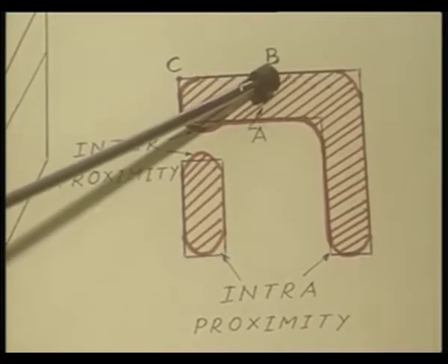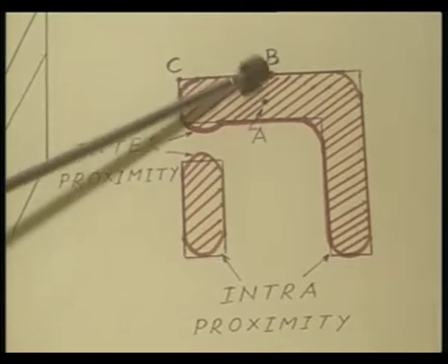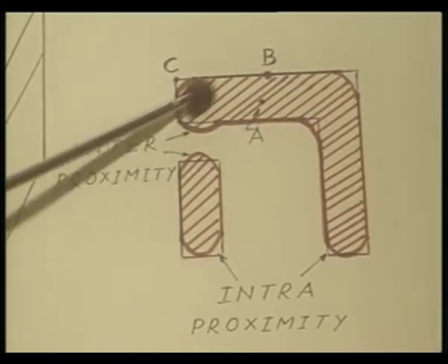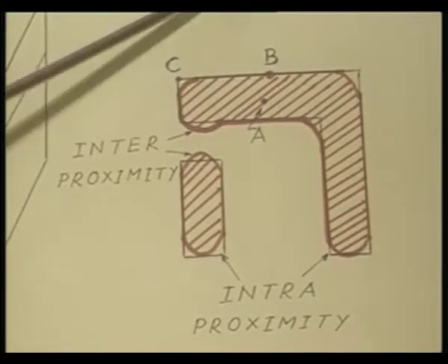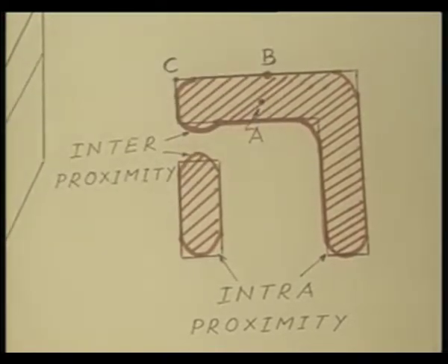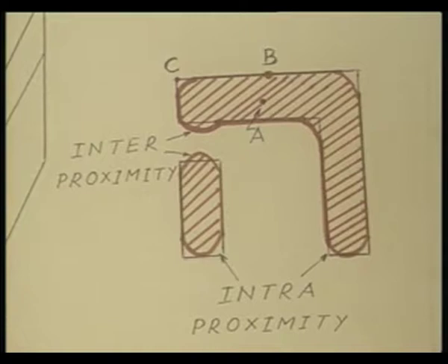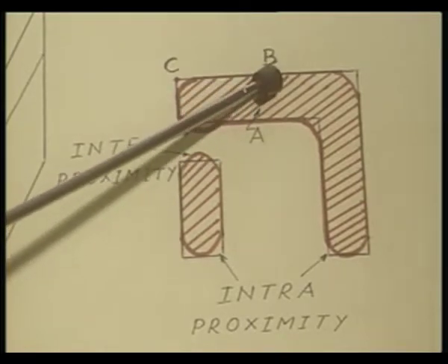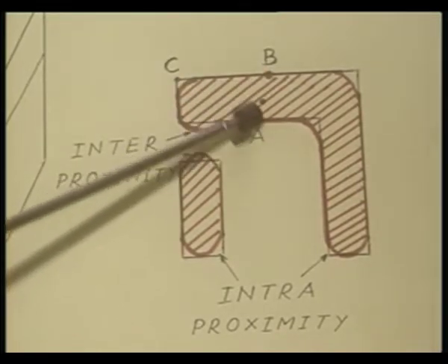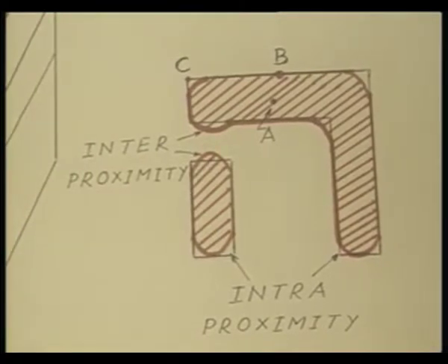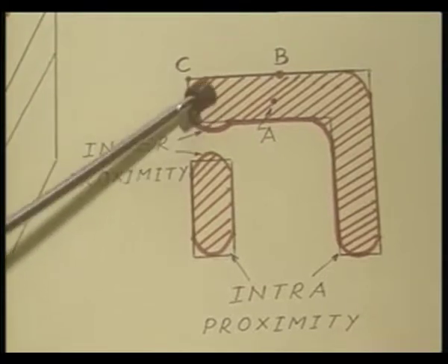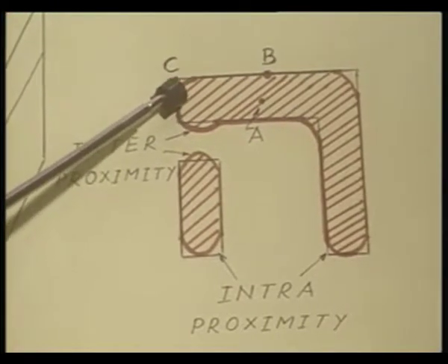Only points which are lying on this side of point B receive the E-beam irradiation, whereas all the points lying on the other side of point B do not receive the E-beam radiation. Therefore, in effect point B is receiving only half of the total E-beam radiation that is received by point A. Point C is of course at a still more disadvantageous position.